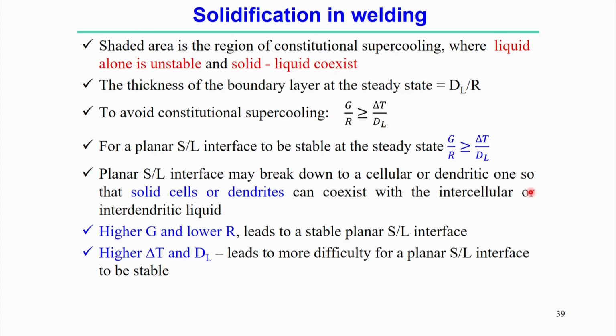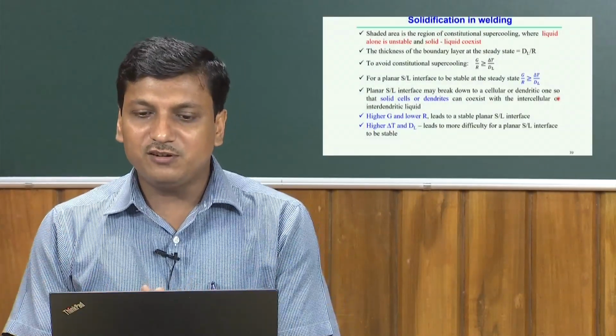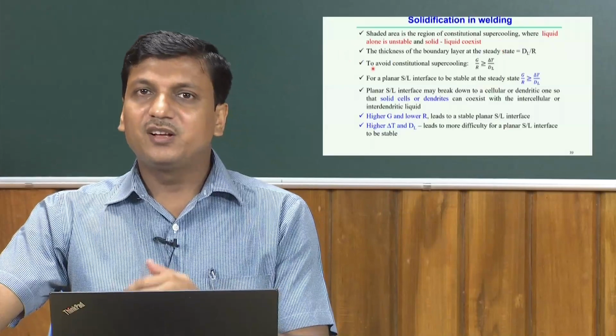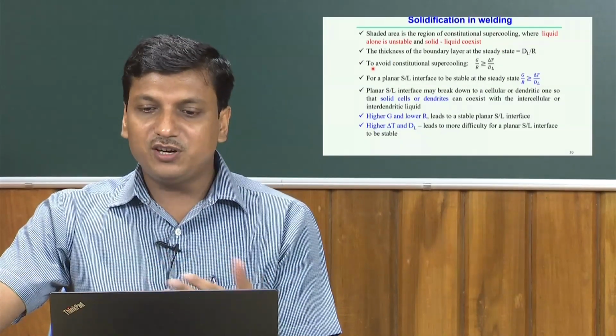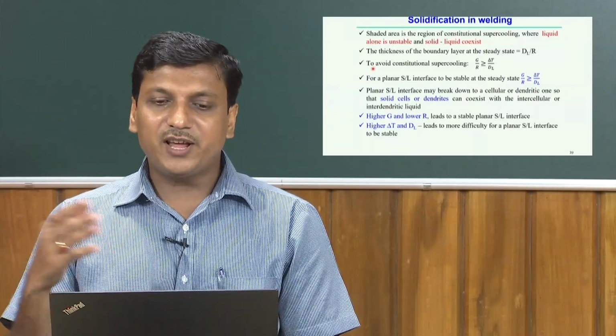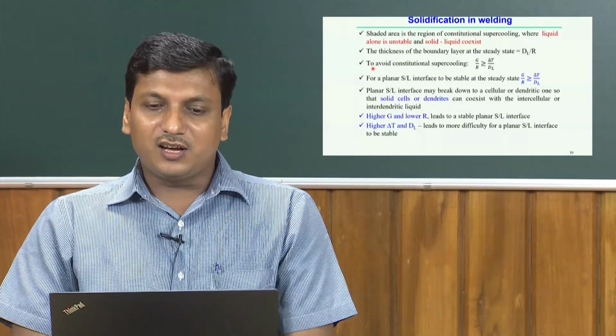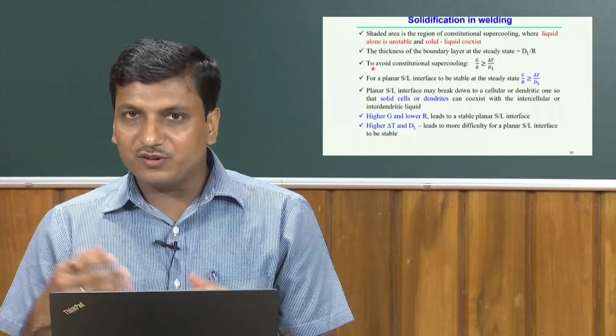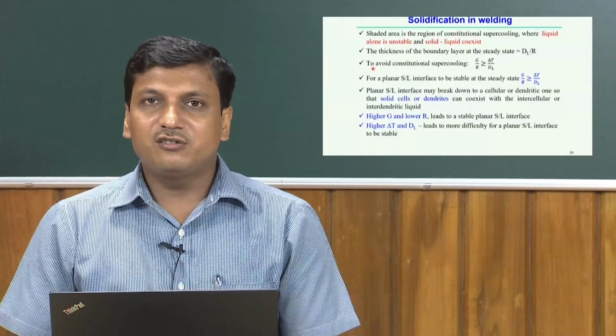So, this mathematical condition is sometimes helpful to quantitatively explain the solidification behavior, the driving mechanism, whether constitutional supercooling exists or not, and based on that the type of nucleation, whether it is homogeneous or heterogeneous, is better explained by these mathematical conditions. Now, constitutional supercooling can also be used to explain whether the planar solid liquid interface remains stable or breaks down.